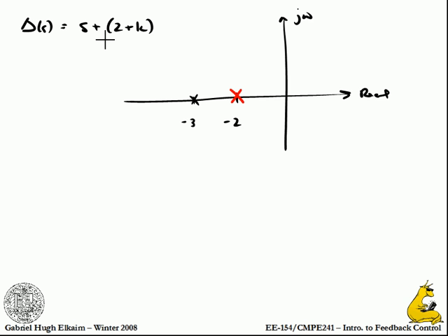What about when K equals 2? -4, right? What about when K equals 100? Where's it going, right? The whole point is that this root is taking off in this direction, right? It's taking off in that direction as a function of K. All right? So I can pick any point here, and I can actually determine that if this is the -5, then K equals 3. All right?